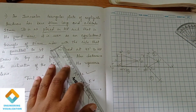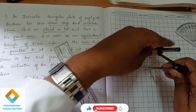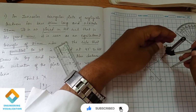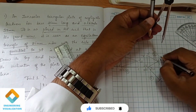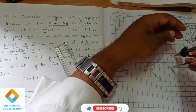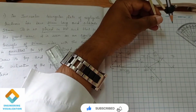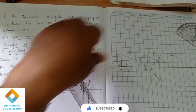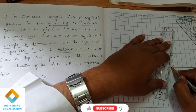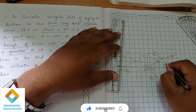Drawing a line. Now measuring this end, because this end A dash B dash is parallel to VP, I'm going to cut the arc. So this is A dash. Now similarly with the same length we have to construct a triangle, same dimension 25. It is already measured 25. Now we join this. You can see the angle here, it is 45 degrees.